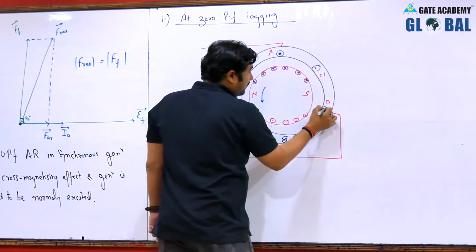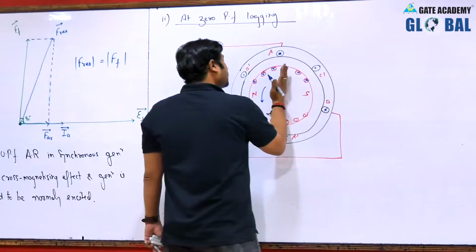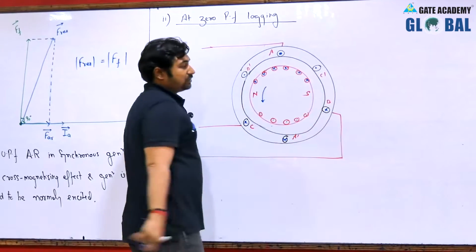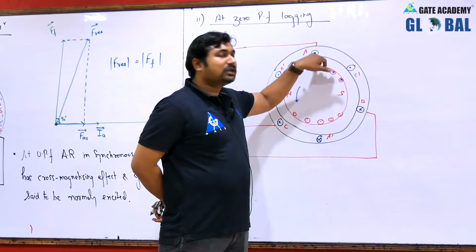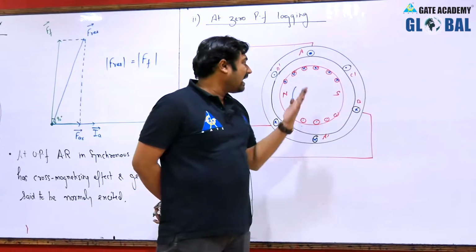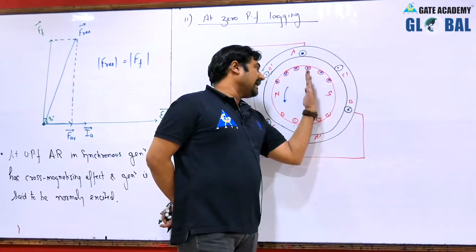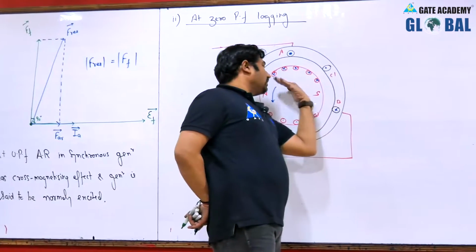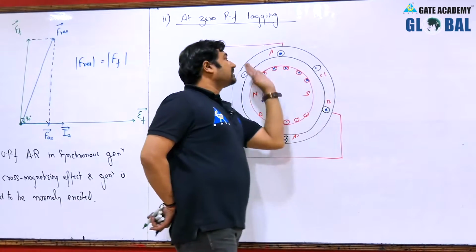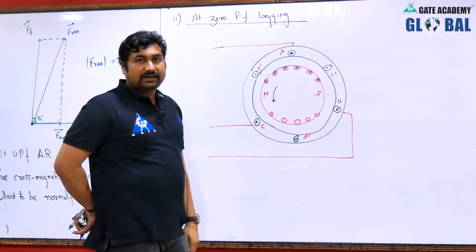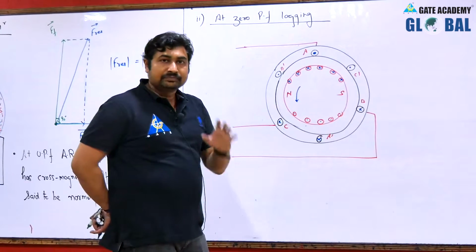But that current will be produced when the rotor field reaches up to this position. Since it is not possible to represent the lag and lead in terms of dot and cross, I have taken an alternative approach and provided this rotor itself 90 degrees ahead, then the current starts flowing into the stator conductor. I am hoping you are able to understand.